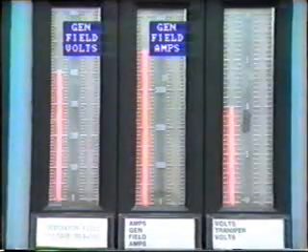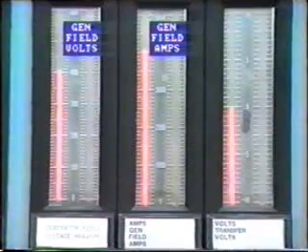Similarly, the voltage regulators are relatively slow to adjust the excitation of the generators and so meet the change in demand for reactive power. So even in this steady-state, stable condition, slight changes are always occurring to the flow of real and reactive power along the transmission lines. Consequently, the load angle or power angle is also changing continuously. Now, what is this power angle?